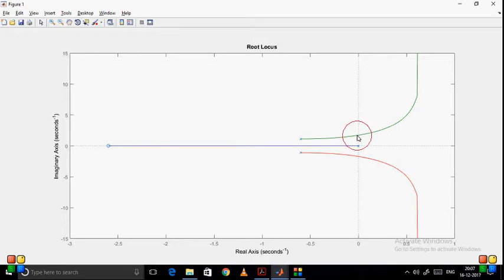At this point, if I look at what K is, just click on it. So the gain is 2.56. As we have seen that we are interested in 2.7, let us move this a bit. Okay, 2.75. If you look at the pole position, the x-axis is positive and the y-axis is also positive, and my interest is the x-axis. Since the x-axis is on the right side of 0, because it is positive, I am interested in the left side. Anything close to 2.7.